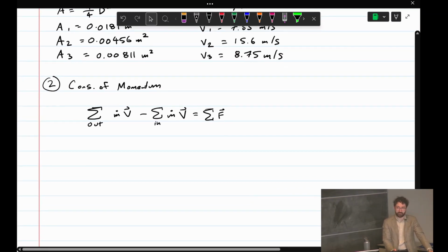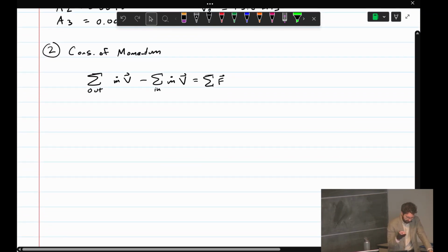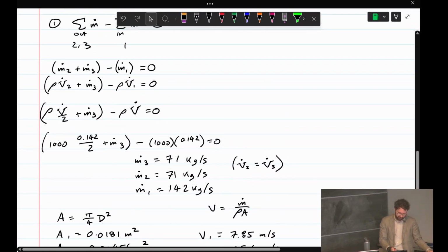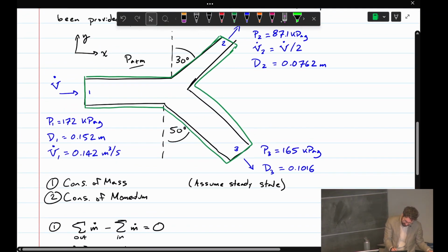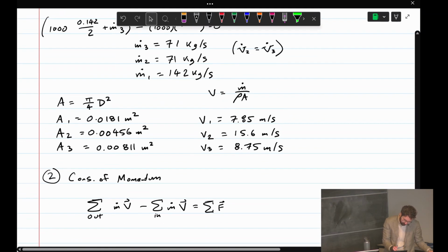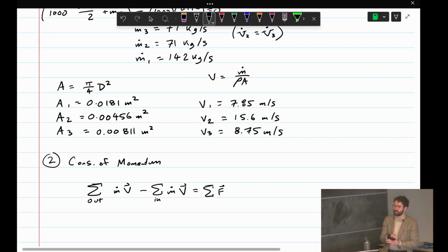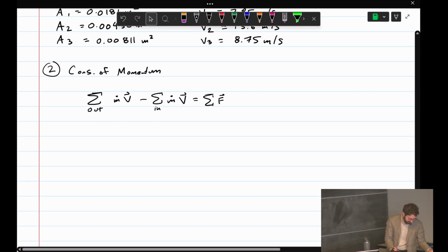Our velocity vectors are going to have components now in our x and y directions, because our outlet velocity actually has a vy and a vx. So the first error source is projecting those using the right angle. The second error source is getting the sign wrong when you are getting those velocity components.